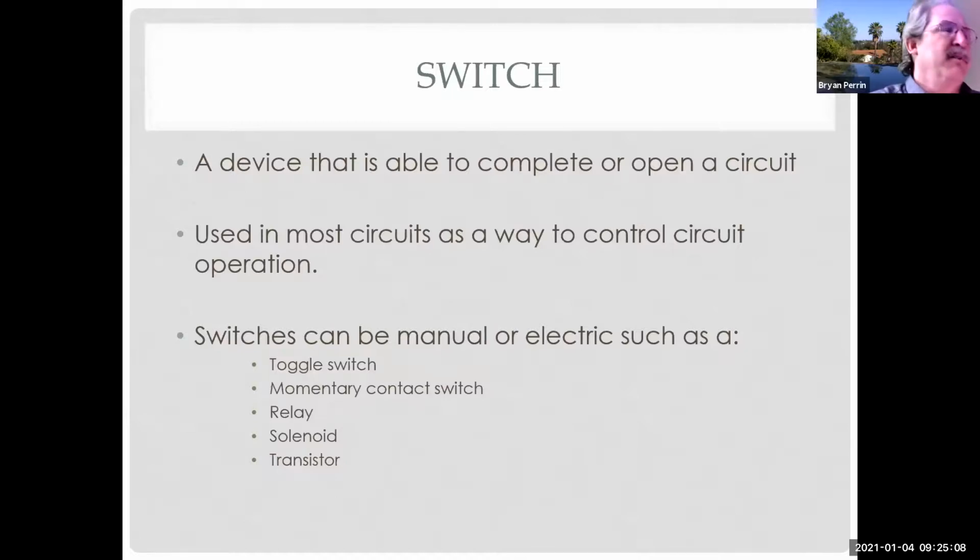I've got some stuff coming up and I'll break it down, because some fuel injectors are 48 volts, some fuel injectors are 95 or even 125 volts. They're very high voltage, so they don't have to flow as many amps to do the same work. So we don't have these huge wires going to the fuel injectors. I'll explain how the math works when we get to Watt's law. But yes, the rule on how we figure it is the same.